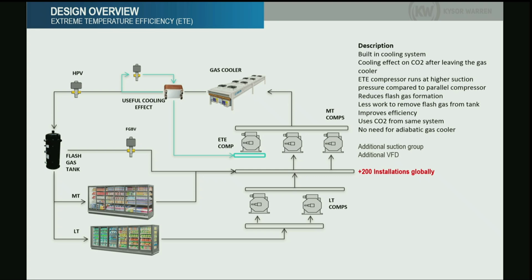How about split condensers, running an oversized 50% or 20%? A split condenser is another option. Yeah, it's another option that has been explored and can be used. Also, those gas coolers all have EC motors, so you have variable capacity on the motors. There are different options and technologies being used, yes. But the split condenser will be used more for low ambient conditions than high ambient conditions.